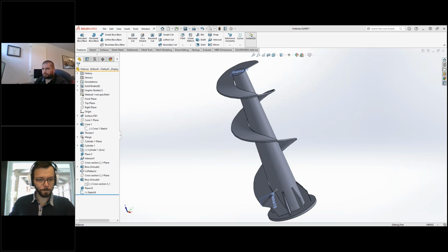Very good. Another one, I guess, for you, Kev. What's the interest for peel.cad if you can import an STL in SolidWorks? Good question. Yes, you saw that I could import an STL in SolidWorks. The difference between peel.cad and SolidWorks is that peel.cad is meant to work with STL files. SolidWorks, we can do it, but you are very limited, and the software is not made to work with meshes. I don't know if you noticed, but I switched the display of the mesh in SolidWorks just because my SolidWorks was lagging a lot, and I didn't have a huge scan, meaning I think we had like 5 or maximum 10 million triangles.